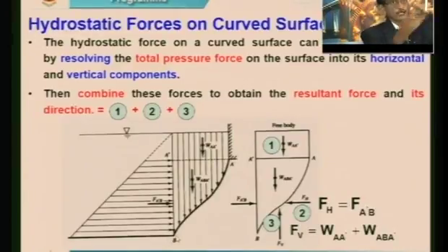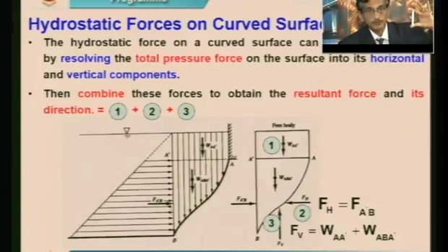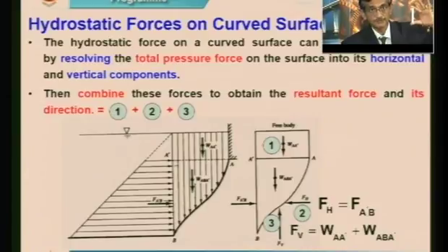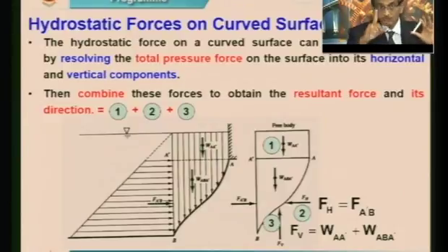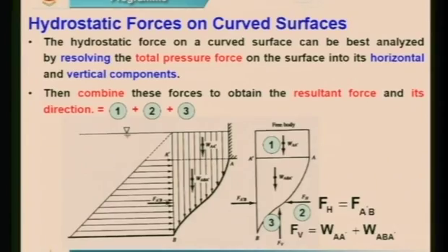I will take a vertical projection. You can see it is in the vertical direction from this point to this point, B and A dash. Now, this one I will take perpendicular as a rectangle and work out. That is actually the hydrostatic horizontal force on a curved surface, right. So, one part is clear to you. We are going to make the horizontal projection of the curved surface on a plane form and calculate the horizontal force with the same formula.